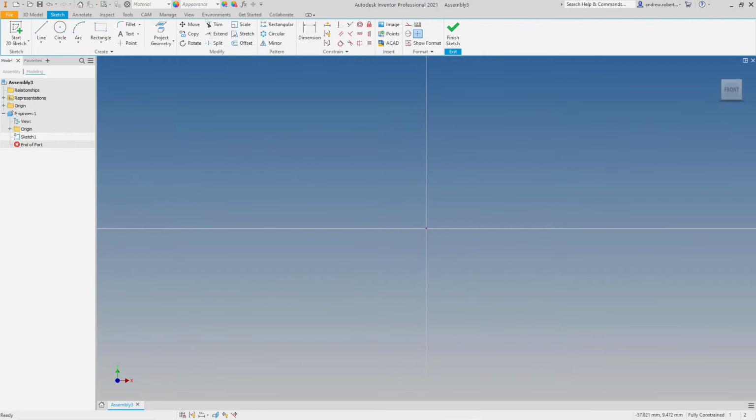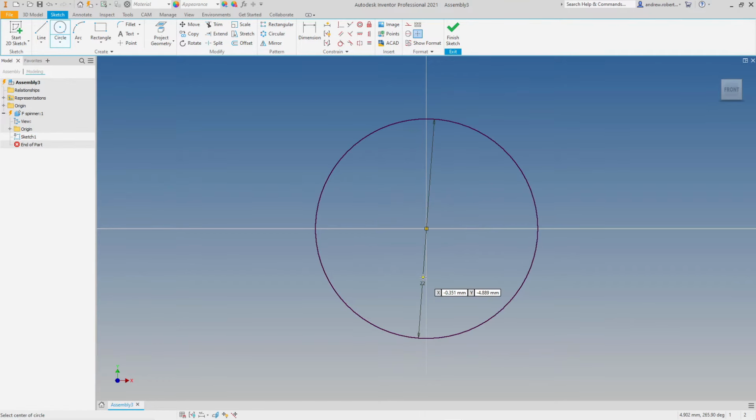Okay team, first thing we're going to do is draw a circle. So up here, left click on circle. We want to snap it to the center. So we all know about snapping. You'll see that that's yellow. Hits the center, snap. Open up our circle. We want it 22 millimeters. So I'm just going to type 22. Enter, and there we go. It's locked on, dimensioned 22 mils.